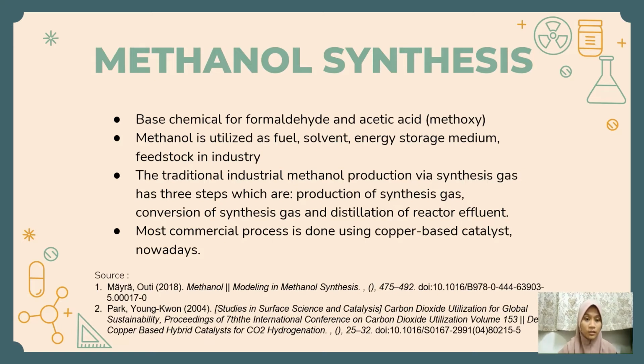The production of methanol is really important as it is utilized as a fuel, solvent, energy storage medium, and also as a feedstock in the industry. There are three steps in the production of methanol via synthesis gas, which are the production of synthesis gas, conversion of synthesis gas, and also the distillation of reactor effluent. Nowadays, the process is done by using a copper-based catalyst.